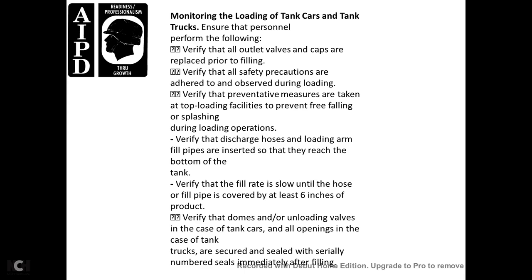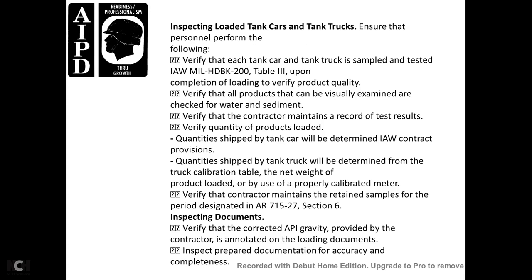Verify the fill rate is slow until the fill pipe is covered by at least 6 inches of the product. Verify the domes and unloading valves in the case of tank cars, and all openings in the case of tank trucks, are secured and sealed with serially numbered seals immediately after filling.